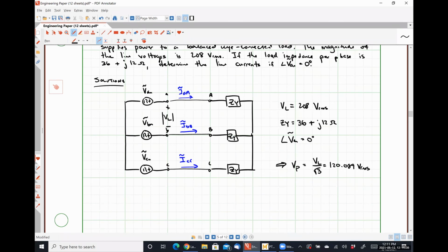So a home installation, typically speaking, won't have a need for a 3-phase. The transformers outside, on the power distribution poles, have a big transformer that's sending out 3-phase. Nethkin Hall, because we have a power lab where we run three-phase machines, actually gets a three-phase connection to the building. But across the street, the IASB and Tech Point are probably just running off of a single phase from that transformer because they have no need to have access to all three phases.